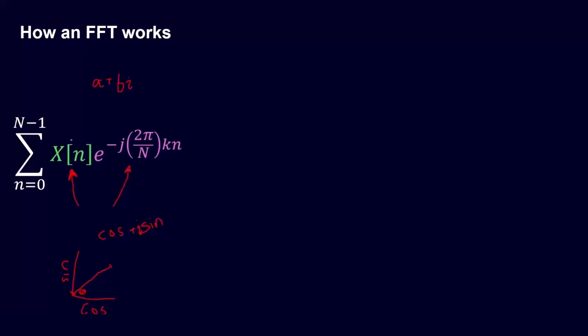Okay, so I'm taking data. I don't know which frequencies it's at, so I'm going to guess at different cosines and sine waves, multiply them together and sum the result. Hopefully it'll be obvious why this is testing the correlation of each of these different frequencies. And once again, we don't know which frequencies are present, so we're going to iteratively go through and guess which frequencies are in the signal.